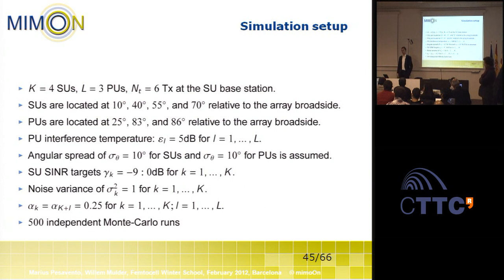For achieving a narrow beam width, you need large apertures. If you have a narrow beam, you are able to determine the user and primary user location, and you are able to point the nulls and boresight correctly. But if your boresight is wide, it's not narrow enough, so you won't be able to separate the interferer. I want to know the hardware limitation, particularly in Femto cells, because of its small size.